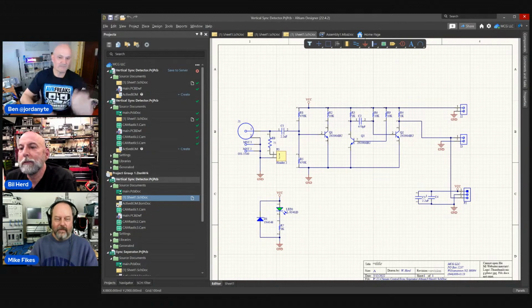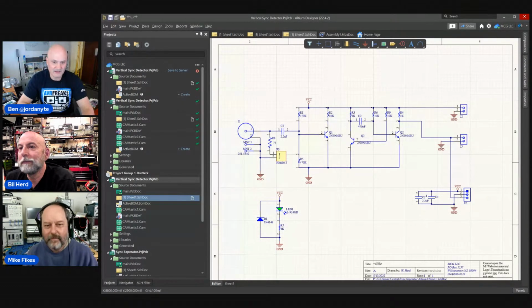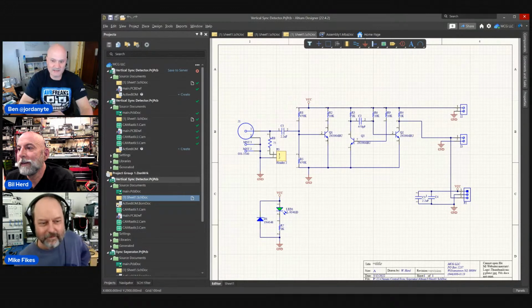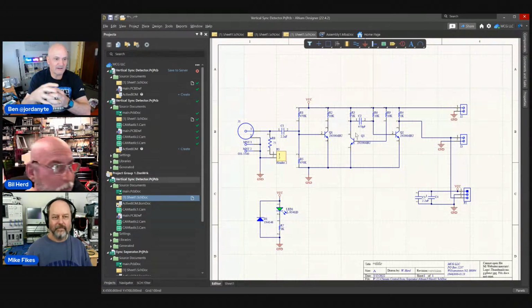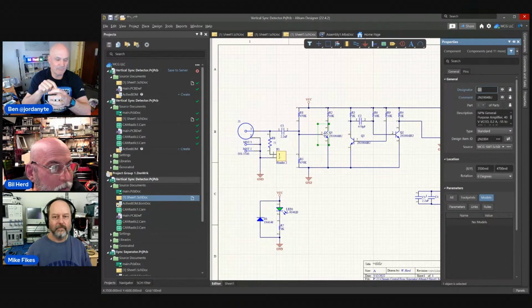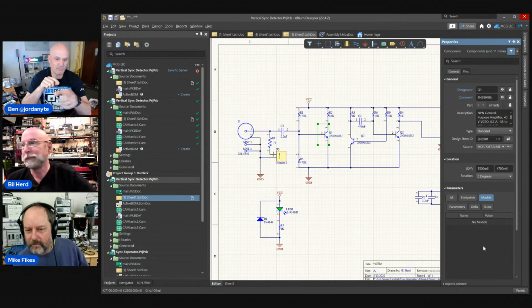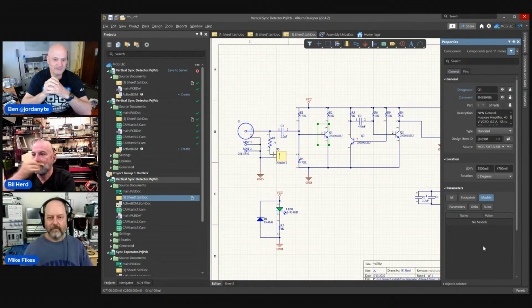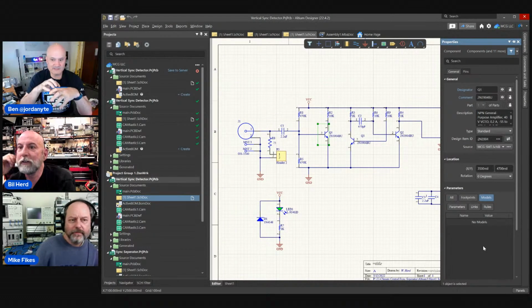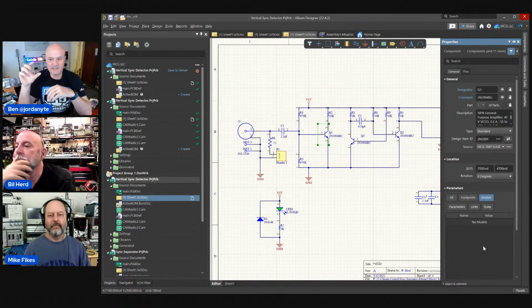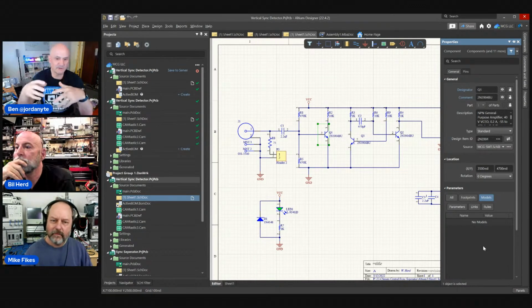But yeah, like this schematic here, I'll do that. But the big problem with doing it in EDA tools is you've got to have models for everything. So even your connectors. So what I used to do was make my connector libraries, and I'd add a Spice source, a parameterized Spice source model, to the connector. So J1 there is an input. I'd give that the Spice source, the input stimulus. Instead, sometimes if I'm just trying to do it quickly, I'll put what's called a compile mask over that.